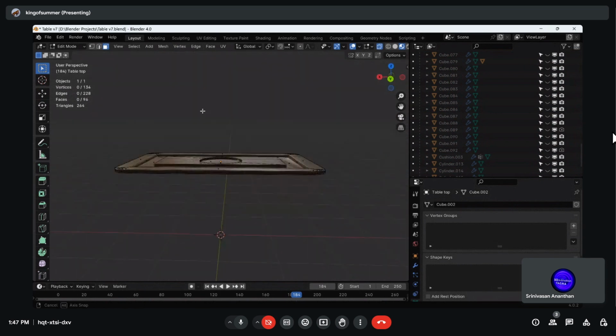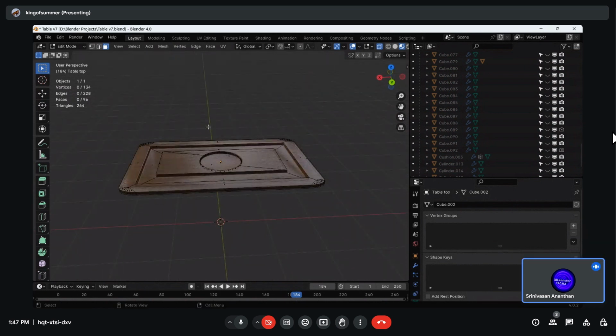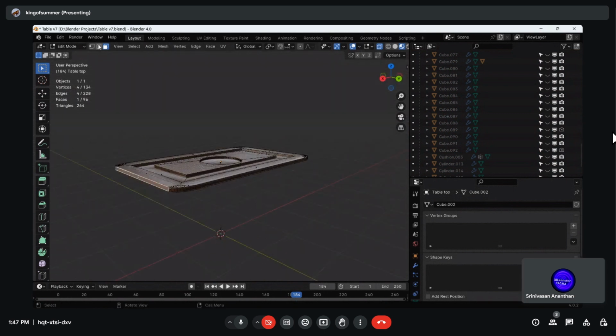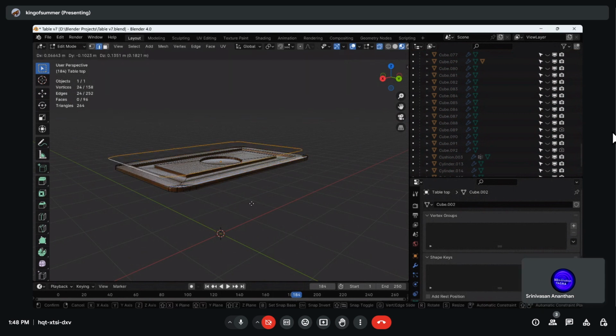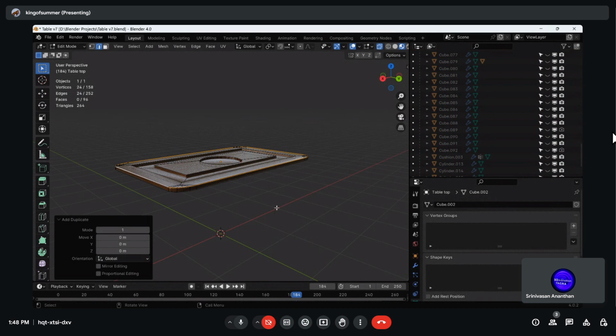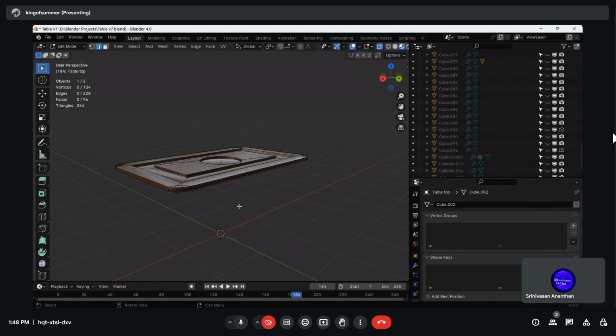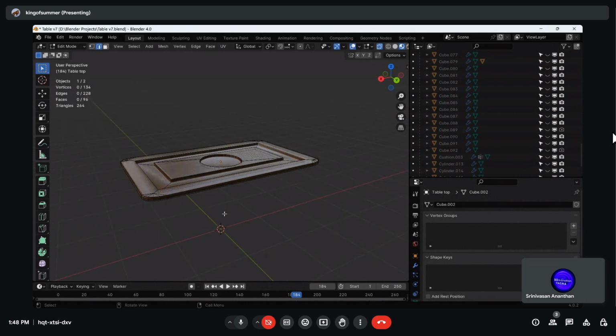Yeah, right. Now select the outermost boundary edges using Alt click. Yeah, correct. Press Alt. Okay, it is in face selection. Go to edge mode and then select. Yes, Alt. Now press Shift D and escape. Then P. Press P on the keyboard. Selection, first one. Now you can go back to object mode.